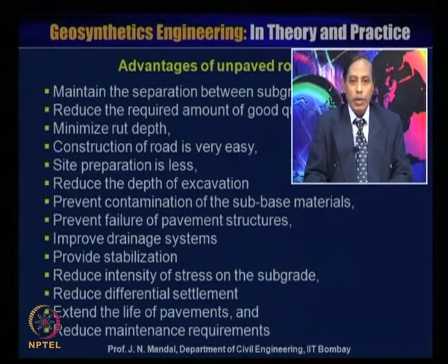Prevent contamination or migration of the subbase material, prevent failure of pavement structure, improve drainage system, provide stabilization, reduce intensity of stress on the subgrade and reduce differential settlement, extend the life of pavement and reduce maintenance requirement.